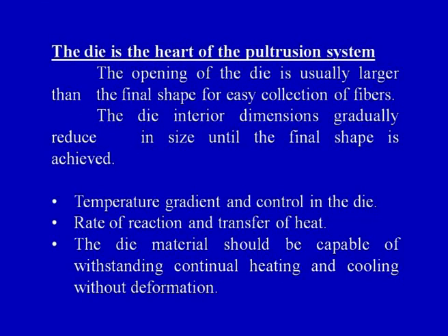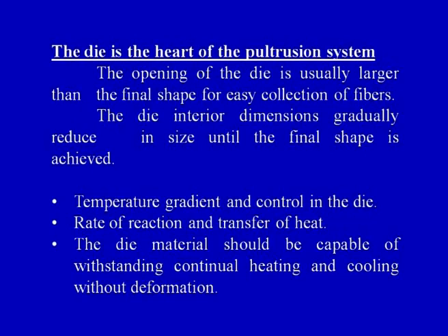The rate of reaction and transfer of heat is also equally important. Rate of reaction means how the curing process takes place and how the heat is transferred to the resin from the heating elements. That has to be designed properly. The die material should be capable of withstanding continual heating and cooling without deformation. So thermal shocks should be avoided in case of the material.